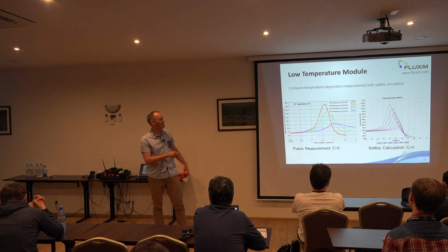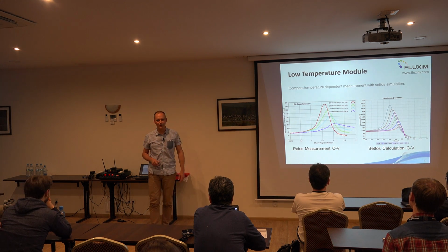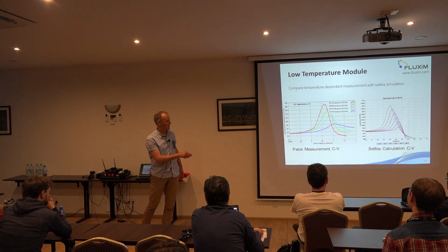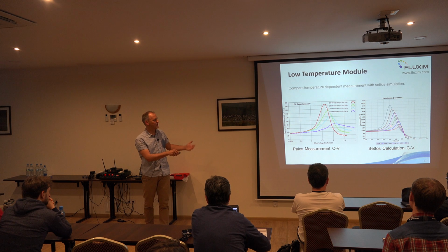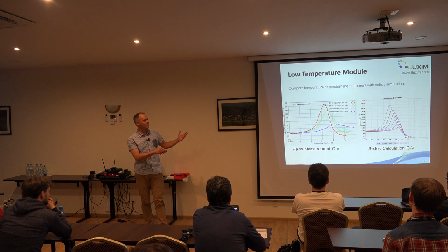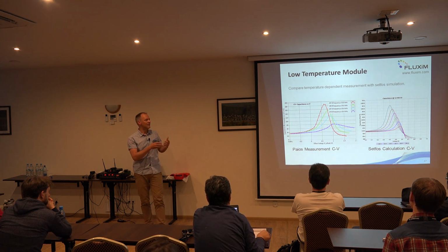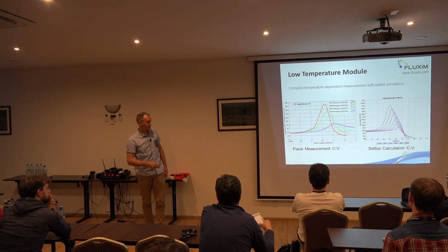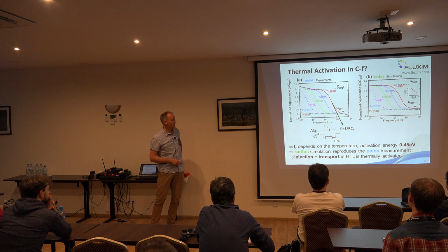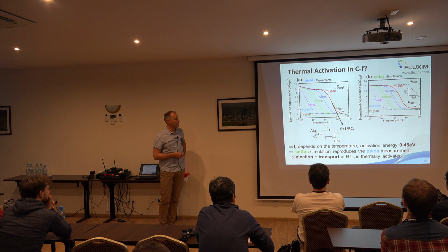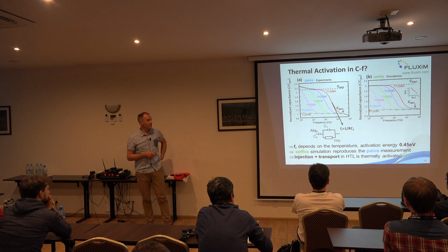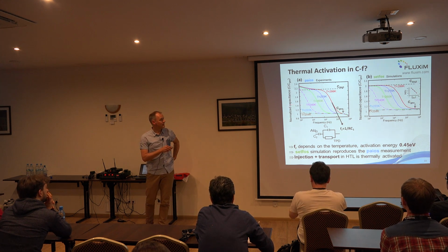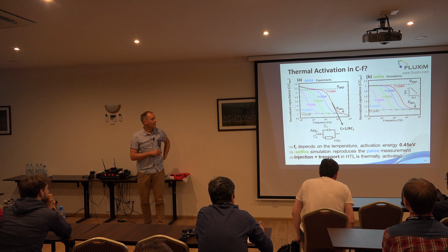It is indeed temperature dependence, and on the right, it's a simulation of capacitance versus voltage, also as a function of temperature, and it behaves very much the same. So with this kind of measurement, you can even try to validate the charge injection model in the software, whether this behaves correctly. And in this bilayer OLED, we can also vary the temperature and look at the thermal activation, where